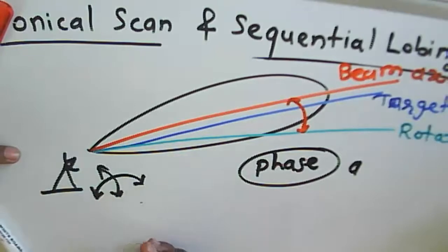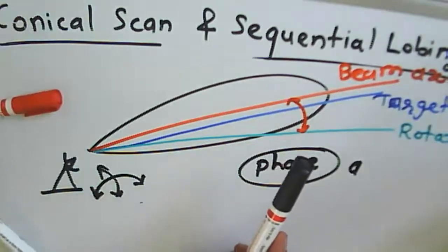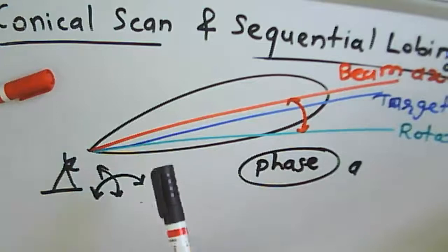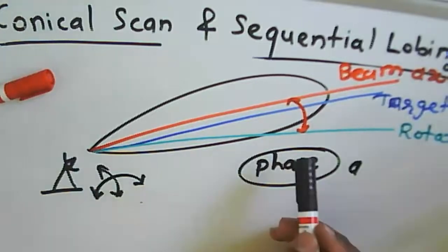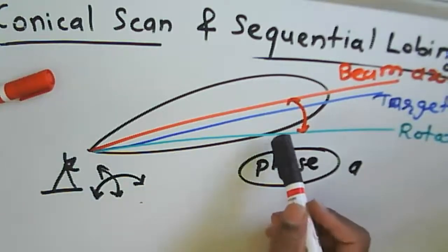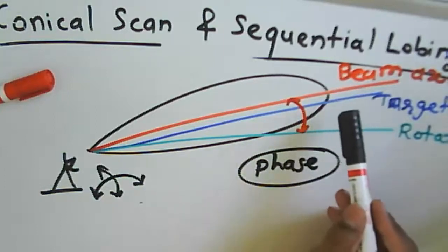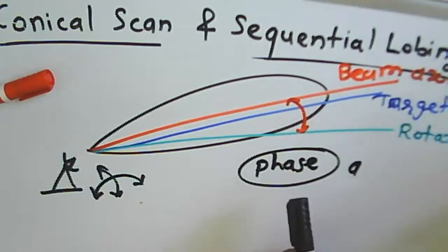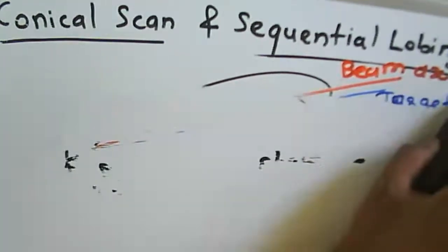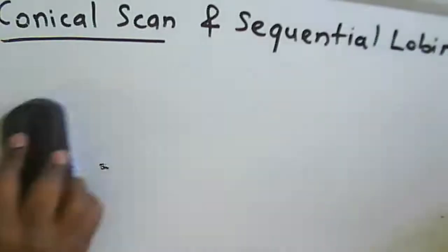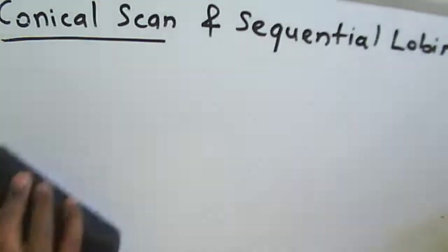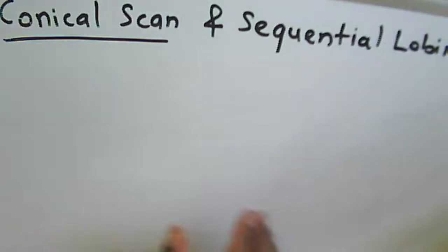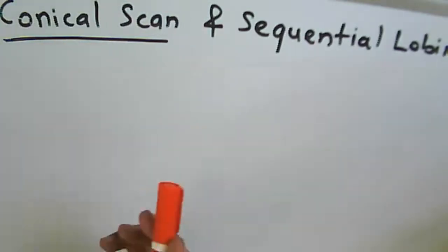So we can find out the azimuth as well as the elevation. So we need to find out where the position of the target is. When the antenna is directed toward the target, the conical scan modulation will have zero amplitude. Through that we can find out the azimuth and the elevation. Now, how do we go about angle tracking using conical scan tracking?